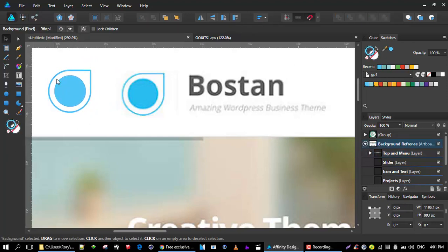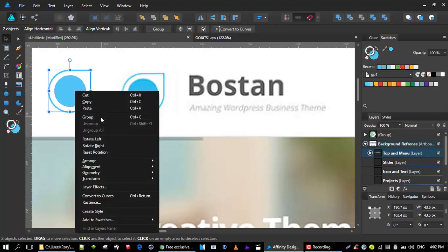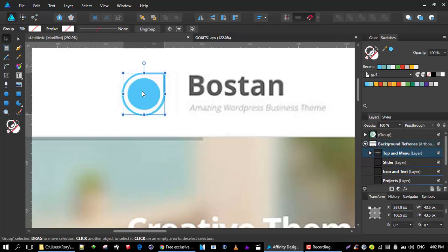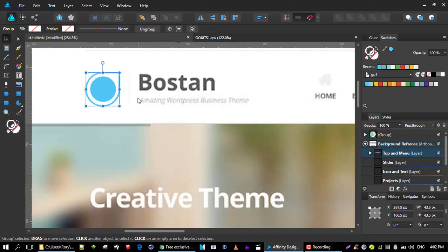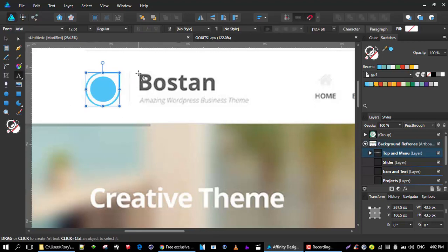We've created that object. And how we got to that outline, you've seen I've used that pie tool, got it nicely aligned, and then converted it to an outline and just used the node selection tool and pulled it out that way. Okay, so there's 101 ways of doing these things. That's just one of the ways that I've chosen to do it. So if we put in that logo, I am going to use the artistic text tool. I'm going to type here now.